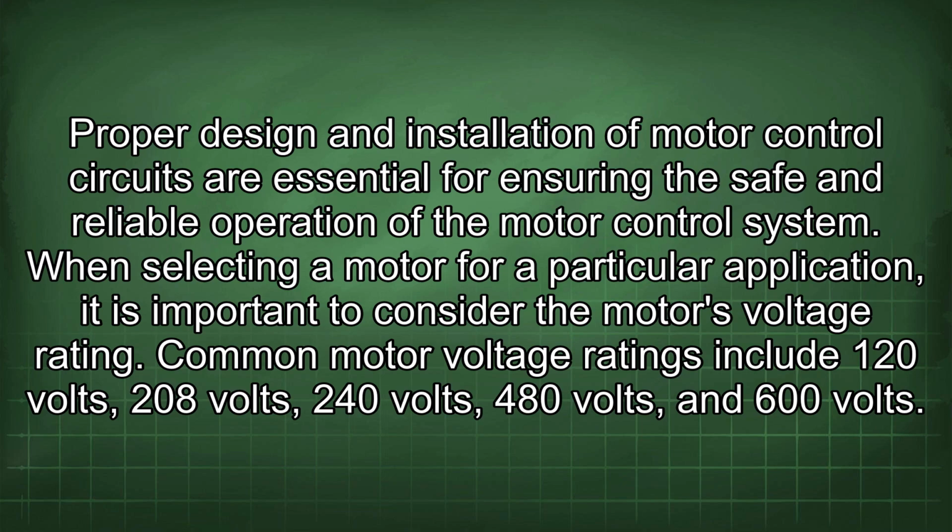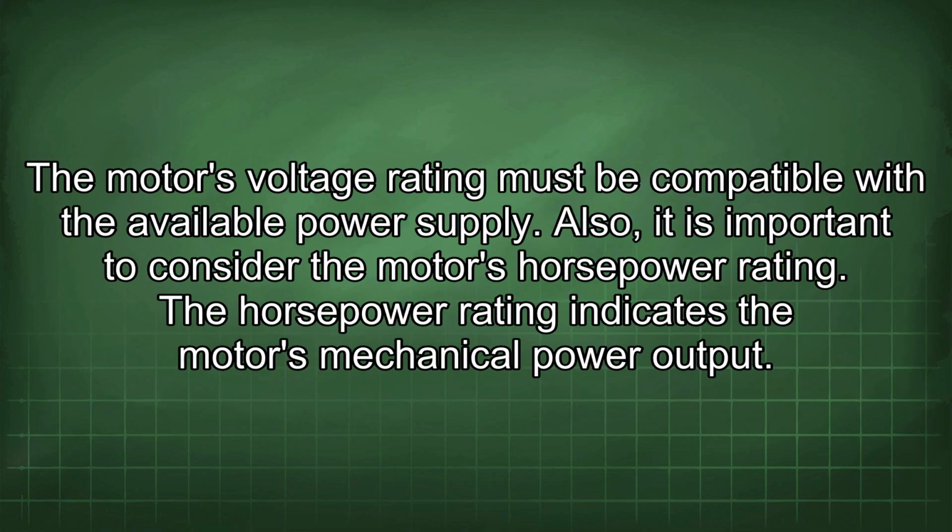When selecting a motor for a particular application, it is important to consider the motor's voltage rating. Common motor voltage ratings include 120 volts, 208 volts, 240 volts, 480 volts, and 600 volts. The motor's voltage rating must be compatible with the available power supply.